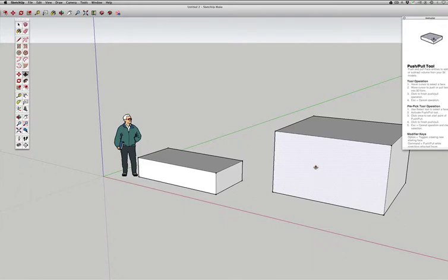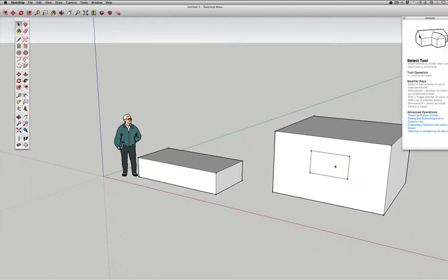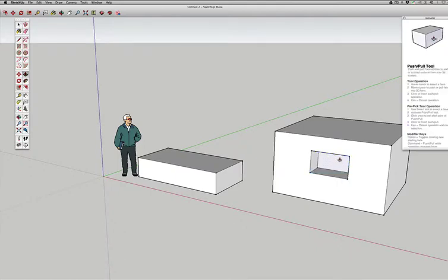And by the way, you can do things like, there's a square there. I can go on top of this. I'm going to hit R for rectangle. I'm going to lock it in on this face. Notice when I make this a square, if I can get this rectangle right. See that? To me, that looks rectangular. You know what? That's actually a perfect square when it does that. Now, if I hit the space bar and just click on that, I can hit P for push. And I can push that.